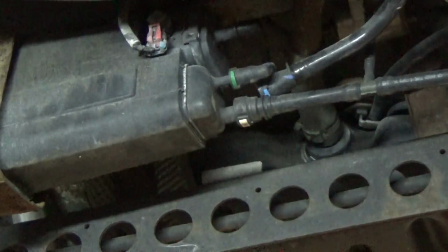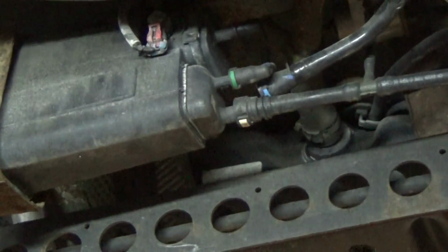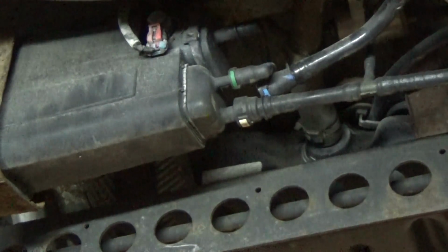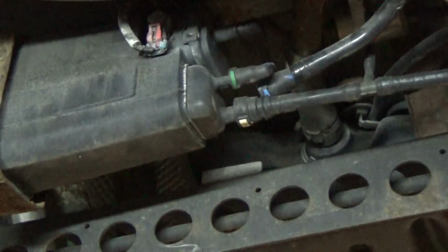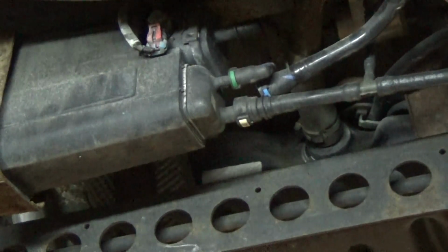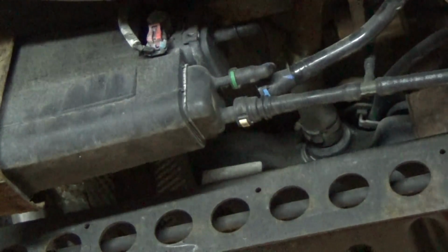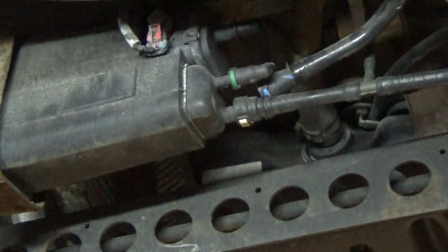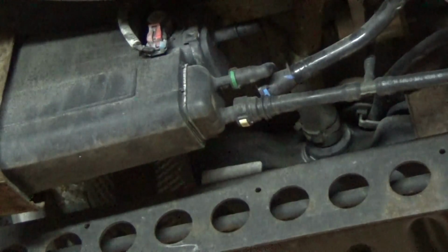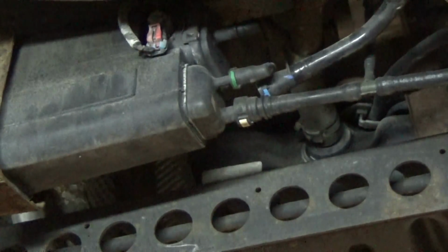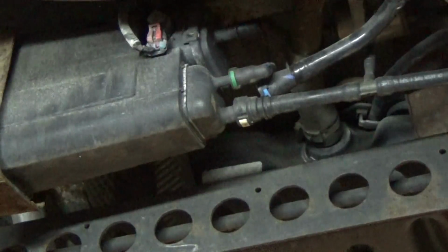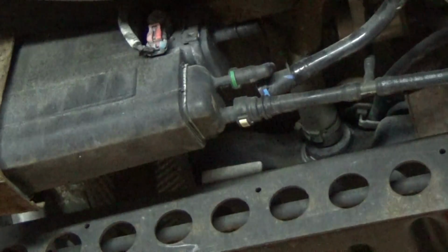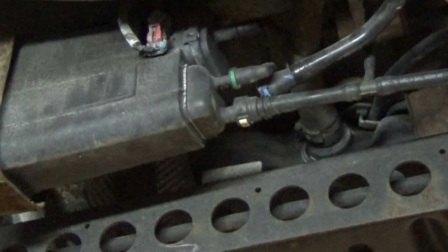And I'm going to repeat my test from earlier. And this time, I can use my finger in order to simulate the vent valve being turned on and off. Now, like I did in the past, I'm going to do the purge and seal. And all I simply need to do is when I hit the increase button, it automatically closes the vent valve, which you heard, and we are pulling a vacuum very quickly. So then I hit system seal, that turns the purge valve off. And we came up to about 12 millimeters of mercury, which would have been about 6 inches of water.